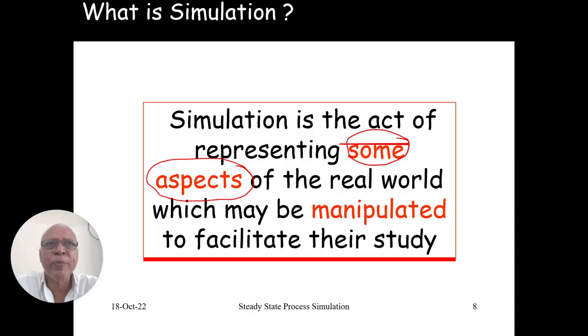So when you are developing the mathematical equations, why do I have to write equations representing the conversion as a function of pressure, or any other such variable which is affecting conversion? This is not the purpose for which you started developing the model. So limit yourself to the so-called objective in developing the model. As you keep on incorporating more and more process variables, the model can become complex and it may pose some problems while solving the model equations.